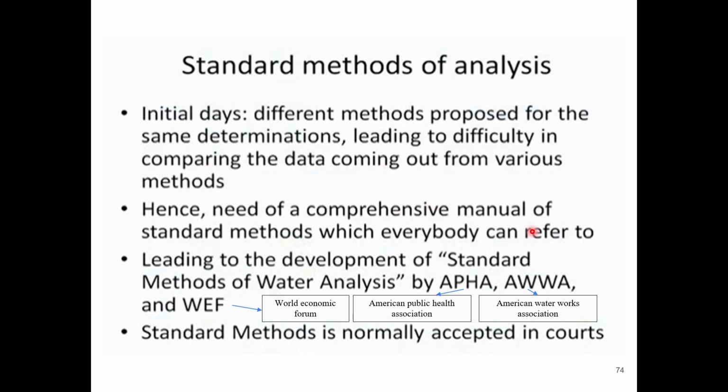Hence, the need for a comprehensive manual of standard methods, which everybody could refer to, was very important, and that led to the development of standard methods of water analysis, suggested by three organizations: APHA, the American Public Health Association, AWWA, the American Waterworks Association, and WEF, the Water Environment Federation. The standard methods are accepted in courts. So when there is a legal dispute, these methods help in providing a solution.